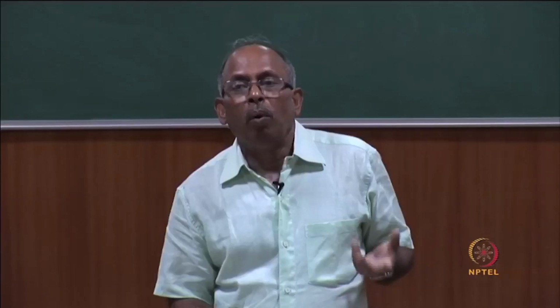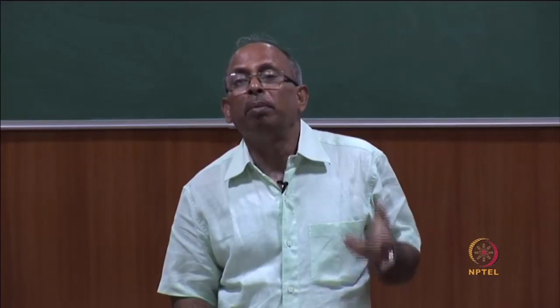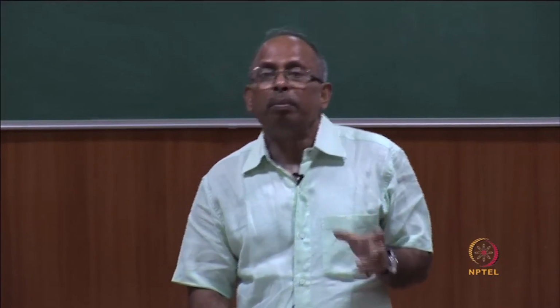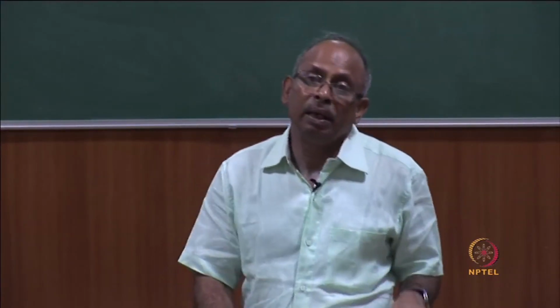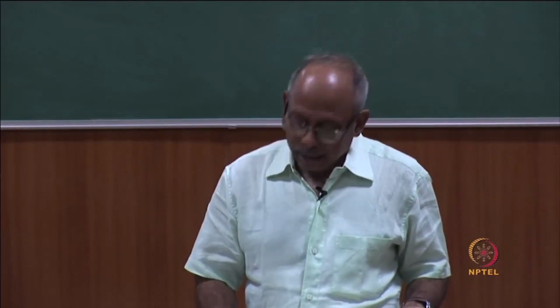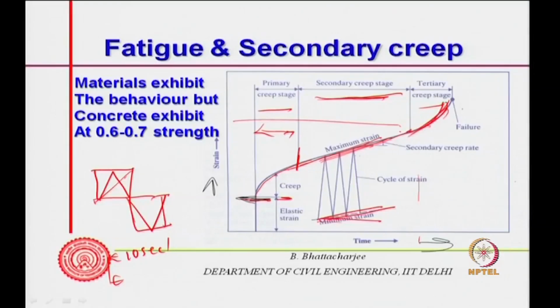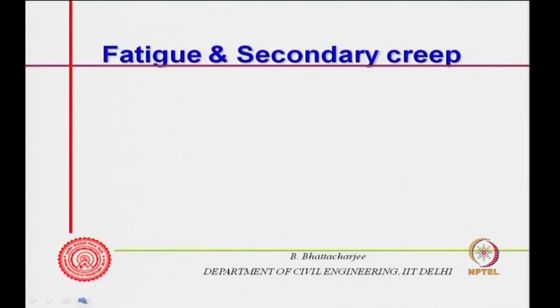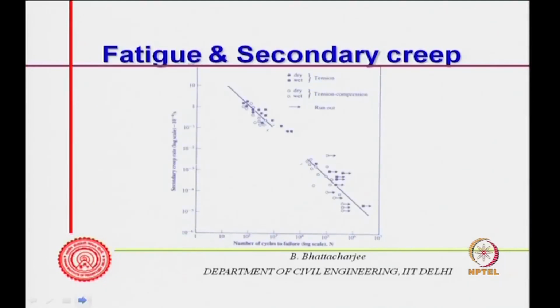Therefore, one can relate the fatigue strength, or the number of cycles it can withstand, to the secondary creep rate. So, this is the secondary creep rate, strain per unit time. If you look at this strain per unit time, one can relate this, and this is what has been done experimentally. People have tried to find out for concrete as well, in tension or tension and compression, for various kinds of materials, one can think in terms of this.